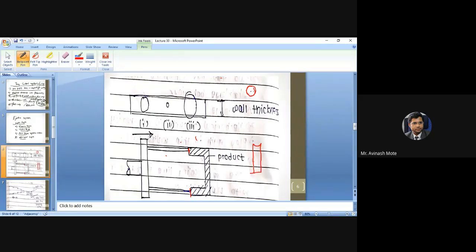Got it? So this kind of surface at the tip of the pin, because you have a cylindrical component, the surface contour and your pin contour will be exactly matched. Are you observing now? If the alignment is proper, the requirement of force will be less. That's what I want to tell. So this is called the pin type ejection system.